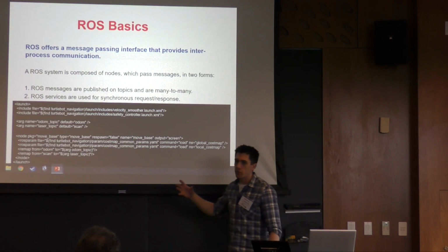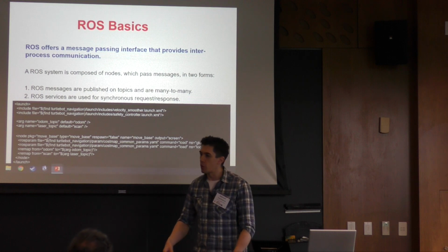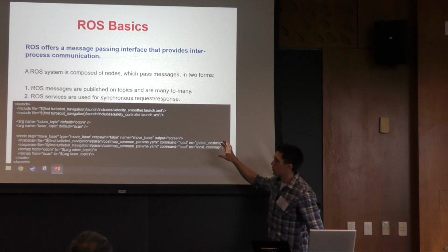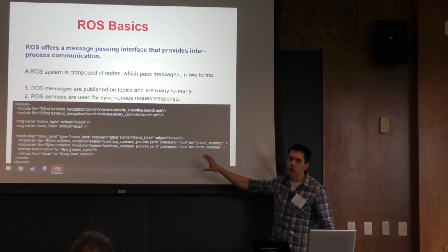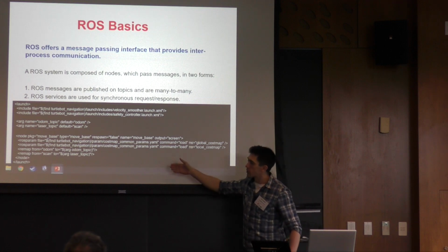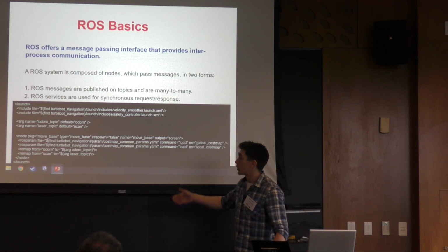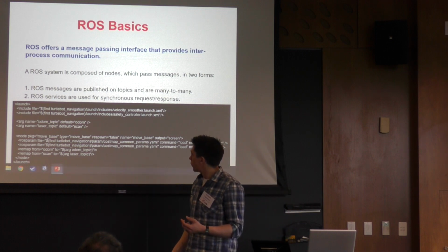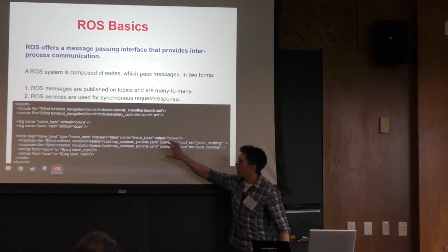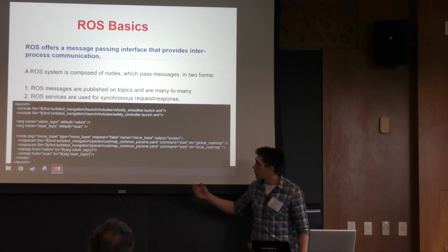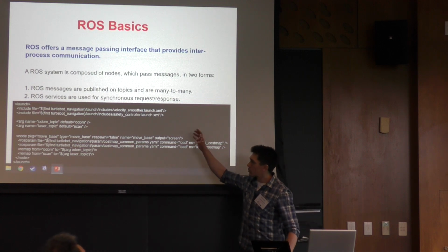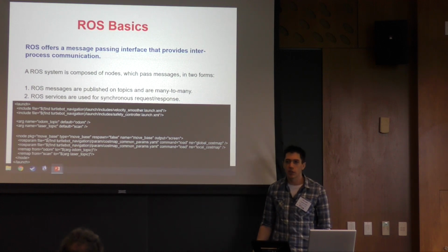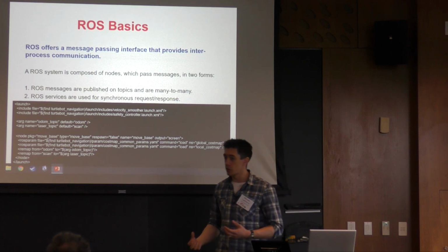All of these nodes can be launched in a number of ways, but the most basic is just to have a launch file, an XML formatted file, which specifies all of the arguments for each node, and boots them up. I'll return to how we use different launch files later, but in practice this is where you place all of the parameters for your system and decide what it looks like.